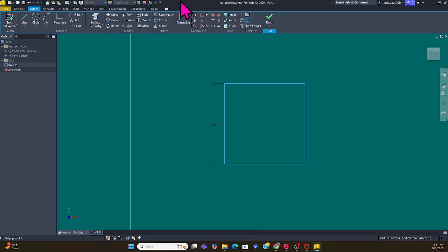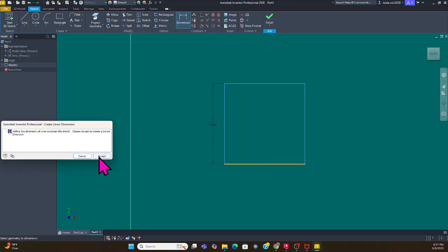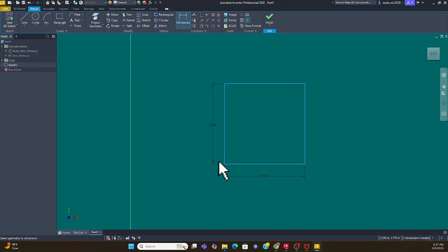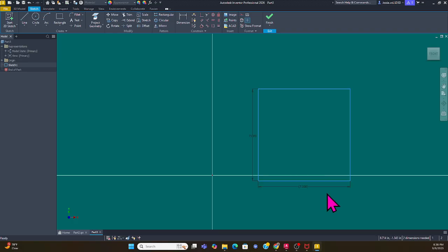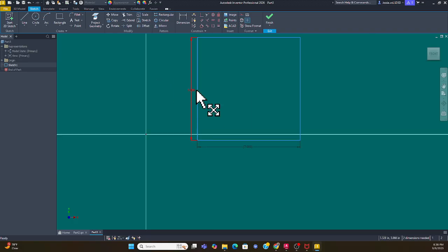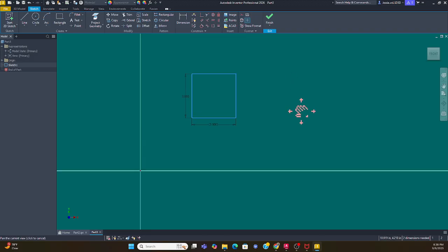And this one right here, if you don't trust me, you can go ahead and take the dimension out, and it's the exact same. There is a constraint that this is the same as the other one. That's why you can see the parentheses. So now here's the thing. If you go in here and you want to change this dimension to a different number, right now it's 3. Let's say you put in 7, for example. The bottom is also changed to 7, as you can see. But what we want is 3, so we're going to change it back to 3. So we got that.